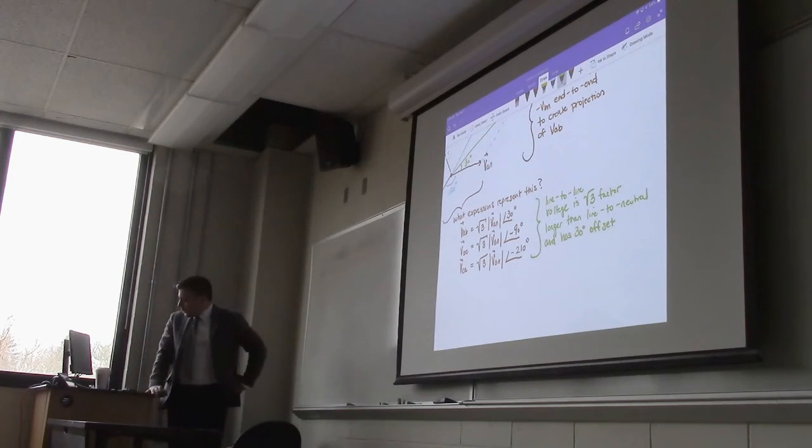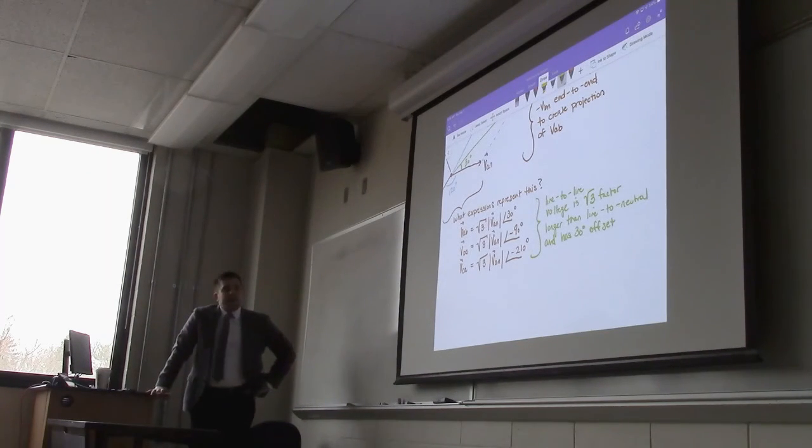If you remember, VBN has an angle of negative 120 degrees, so VBC is negative 90, and VCA would have an angle of positive 120, which is negative 240, and with the 30-degree offset, that brings it back to negative 210, which again reinforces it.